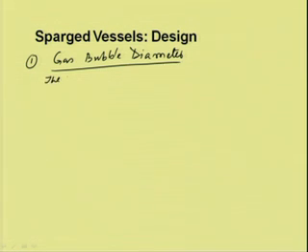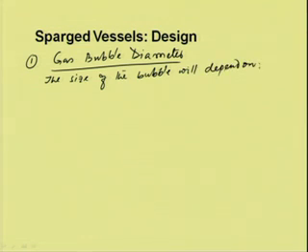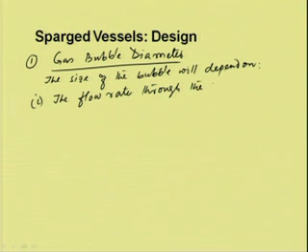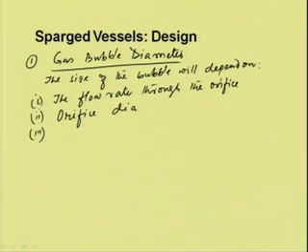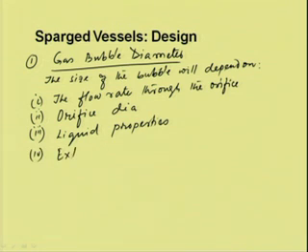The size of the bubble will depend on the flow rate through the orifice, second the orifice diameter, liquid properties, and the extent of turbulence in the liquid.